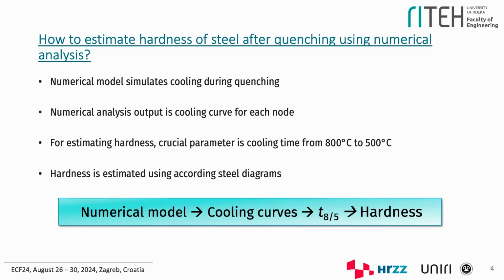The general idea here was to develop a numerical model whose output is cooling curves for each of the nodes. Those cooling curves give us specific information, and that is the cooling time from 800 degrees Celsius to 500 degrees Celsius, which is crucial to later determining the hardness using different geometry diagrams.